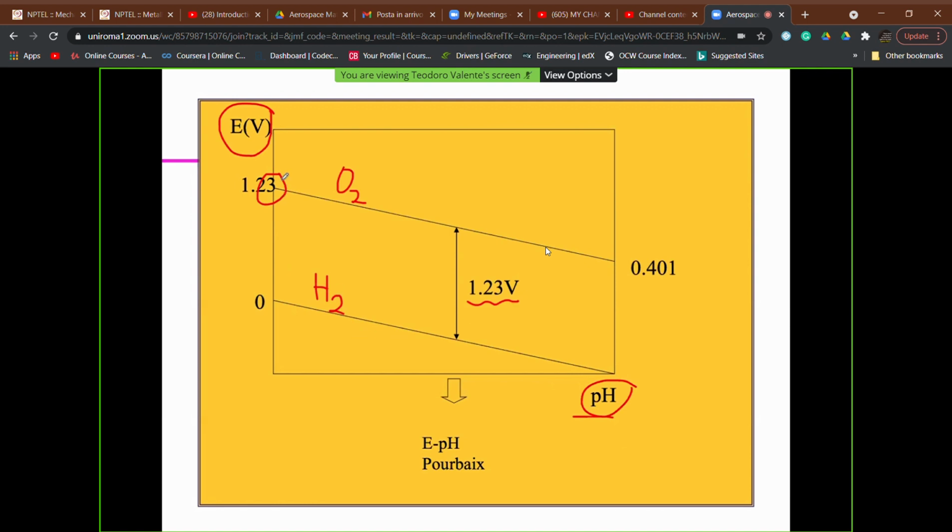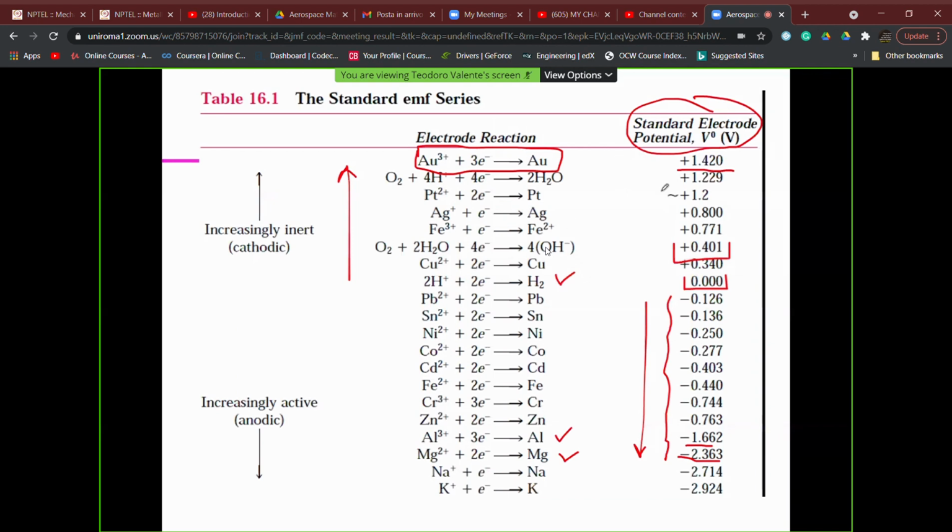And these kinds of diagrams, which we have now simply drawn for the two cathodic reactions we are going to investigate, can be completed by putting on the diagram the values of the potential of the anodic reaction, and thus by comparing the potential of the anodic reaction with the potential of the possible existing cathodic reaction, as we have done conceptually here starting from the E0 value, we can define if from a thermodynamic approach we do have a positive driving force, a difference of potential, to let the corrosion phenomena happen.